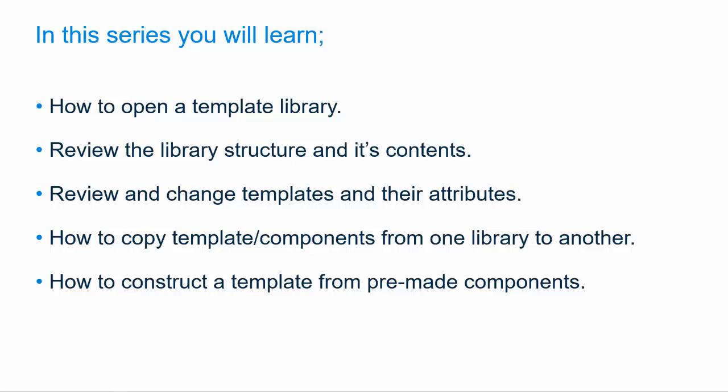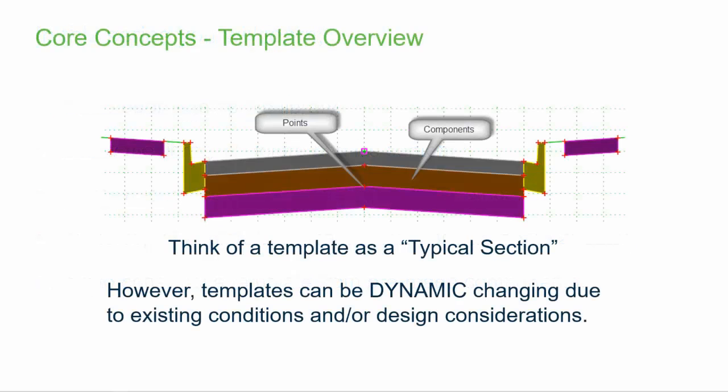What exactly do we mean when we speak of templates and how they're used? Templates are made up of points and components. You can think of them as being sort of a typical section. However, and let me stress this, templates can be quite dynamic and morph due to existing conditions and/or design intent or standards. So, why should you learn and adopt this new technology?